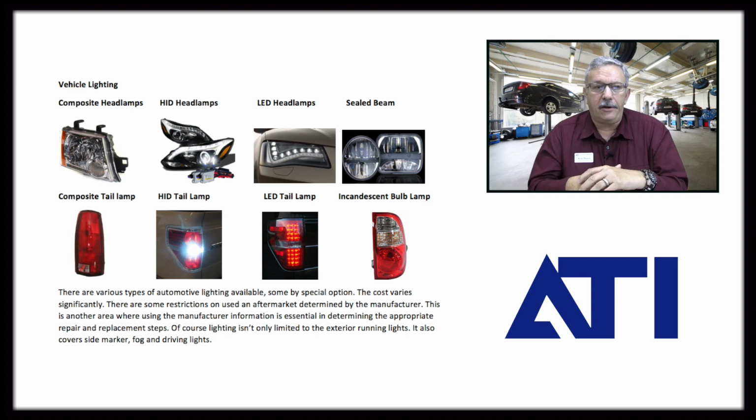So what do I look for? Well, if I just receive the part and I take it out of the box and I see condensation, I'm probably not going to want to use that part. Especially if there's integrated electronics that are bolted to it, because that gives me a question as to, number one, where was it stored, where did it come from, and could it have been in, let's say, a flood damaged vehicle. So just be very observant, as we're being told to order parts in some cases, of where those parts are coming from and the condition of the parts when they arrive.